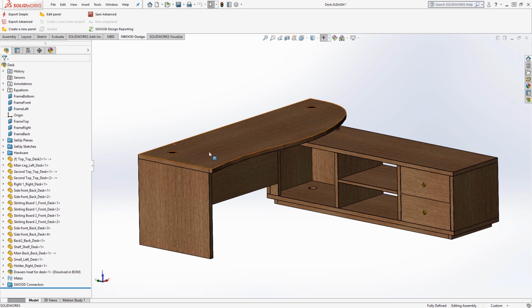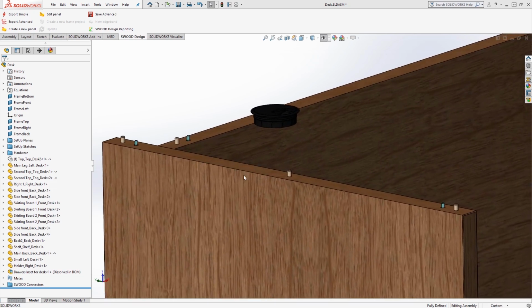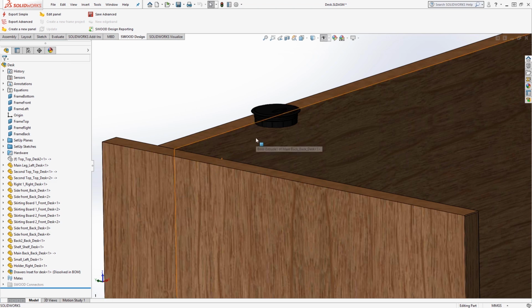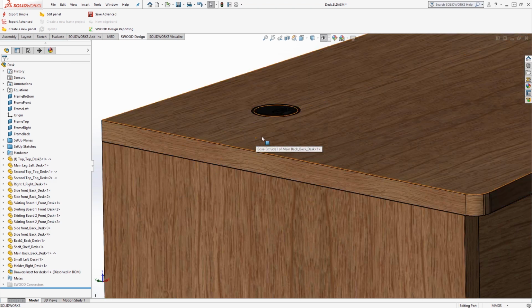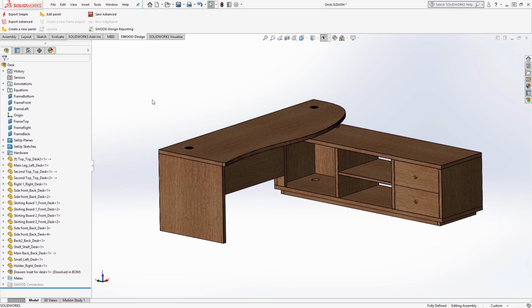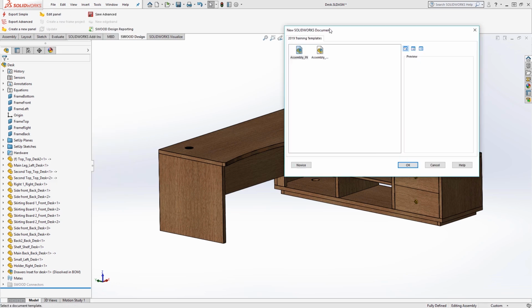The other thing we have to think about at this stage is whether you're going to create an exploded view in Visualize. If you are not going to show the connectors in any renders, it would be worth suppressing them in SOLIDWORKS. Connectors are often small, detailed parts with lots of little faces. Suppressing these can save a lot of polygons that the software has to work out, therefore saving open and render times.